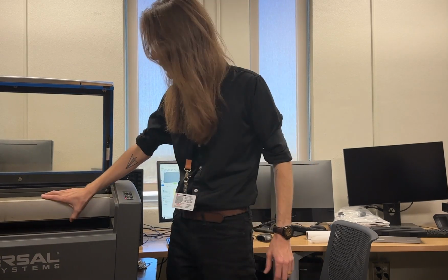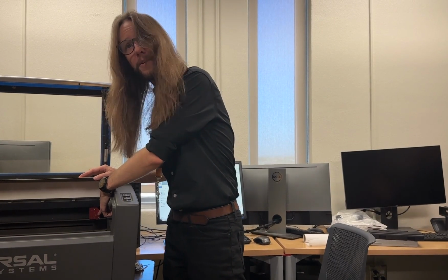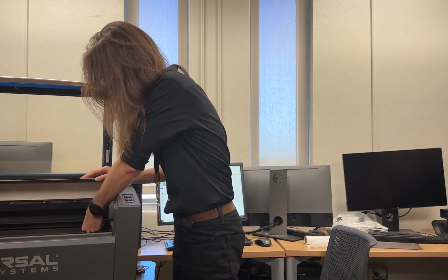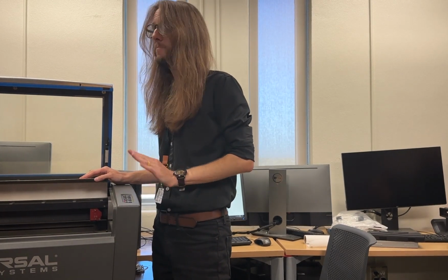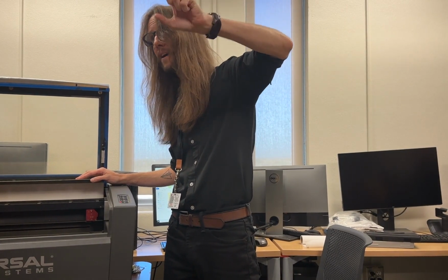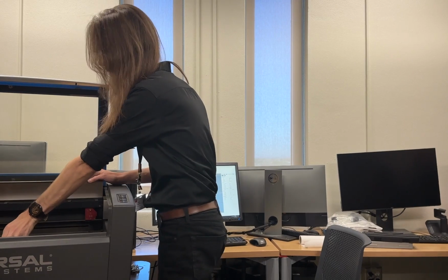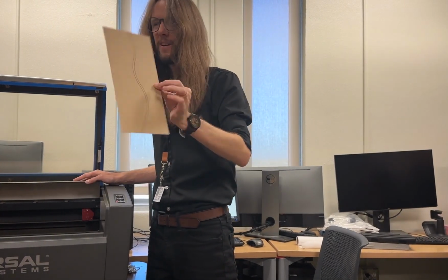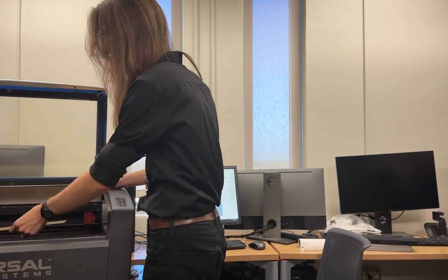Anyway, have a couple things here. Of course, we have the laser here. You'll see that there's a 2.0 on there. It stands for 2 inches, and it means that the laser needs to be exactly 2 inches away from the material, not the bed. So if I have a really thick material, it needs to go 2 inches from the top of that material, right? Pretty simple enough. In most cases, you're not gonna cut anything larger than 1/4 anyway. So maybe not a huge deal.